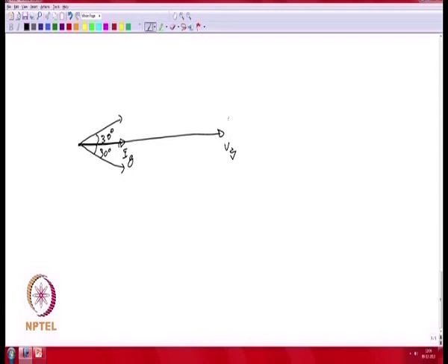And then if you look at what would be the voltage that would be required at the terminal of the power converter. When you are trying to inject leading VARs, you would need a higher terminal voltage. When you are trying to inject lagging VARs, you would require a lower terminal voltage. So you could require, say, about 10% more DC bus voltage when you are operating in, say, a range of such conditions.